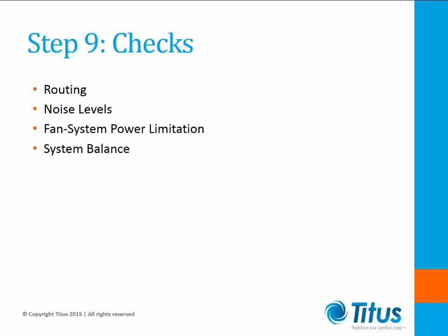Have the ductwork system reviewed for objectionable sound levels if high velocities were required. If you find that you have high sound levels, some options for mitigation of these levels are as follows. Utilize internally lined ductwork. Double wall construction sometimes can reduce sound. Sound attenuators, or even duct lagging are options available to you.